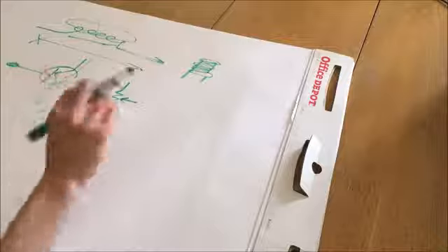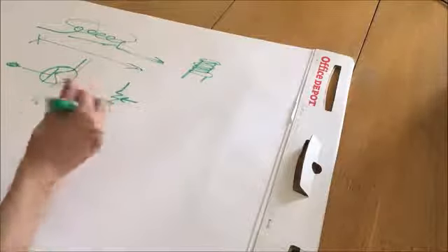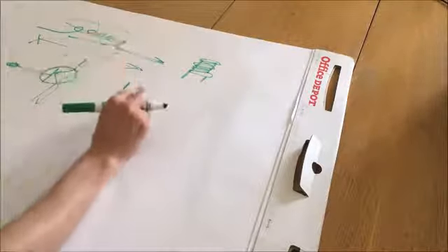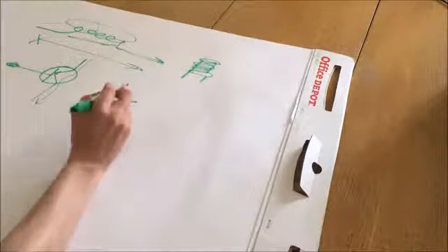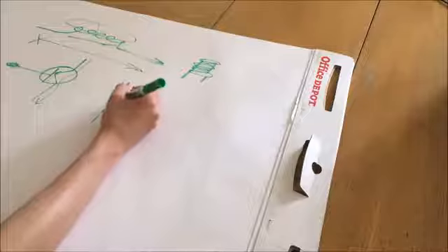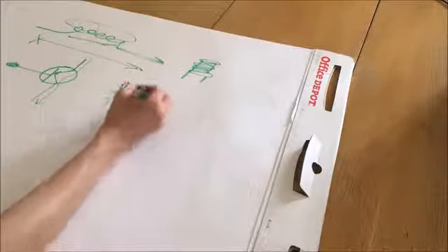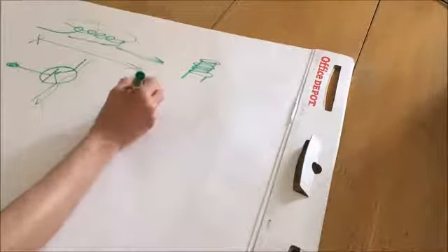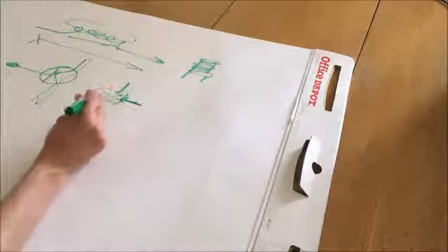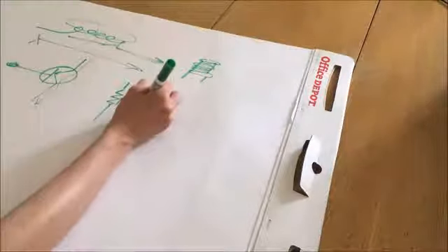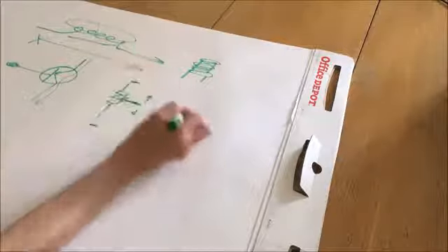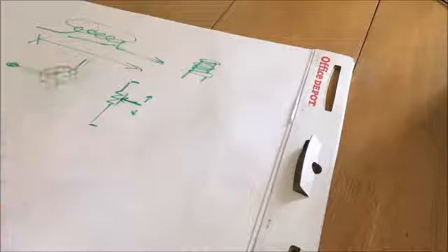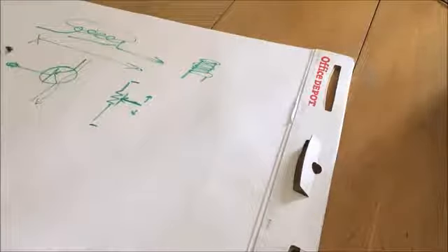And you'll see this often as a dial that you can turn, or what they call a trimmer, where you put a screwdriver in to rotate the control for it. But essentially, you can adjust the resistance of the resistor, and usually this arrow will have an actual center tap on the resistor, so you can move it higher or lower with respect to one side of the resistor and the other side. But those are basically the components you're going to run into. Anything more complicated than this, I'll cover.